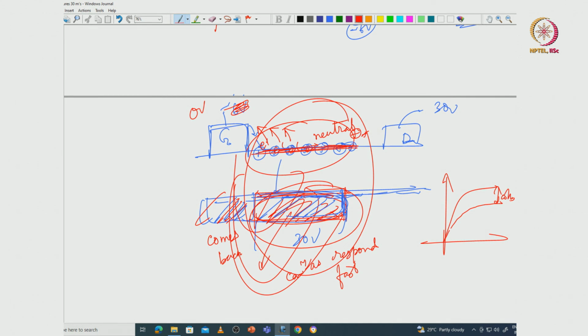So that is a bad thing, and because of this collapse your current will be low. In a real microwave signal, when you are putting in an input signal and you are going to amplify it, you are kind of mimicking this large signal pulse only. So if your current has dropped by say 30%, then in a real RF power amplifier your current will be 30% lower, and that is a significant setback, because you are not able to get as much current as you want. So the way to solve it is of course twofold.